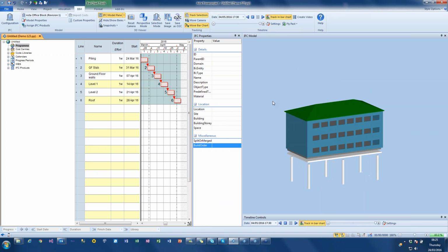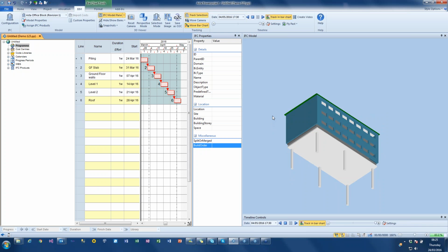Now the cuts I've just made, I've made inside Powerproject. They do not have to stay, I can remove them, but I haven't actually modified the IFC. The IFC is still just one single slab for each of those. Powerproject gives me the ability to do it as I want to do it, and I can split walls, I can split any objects I want.